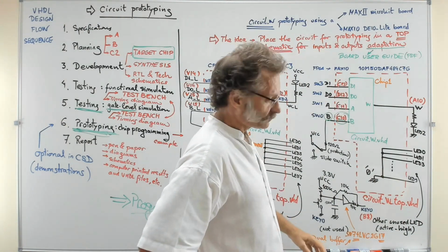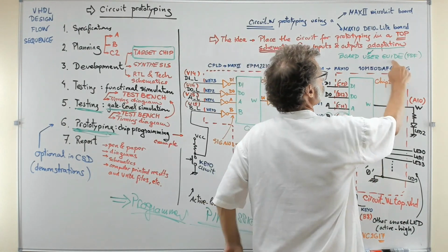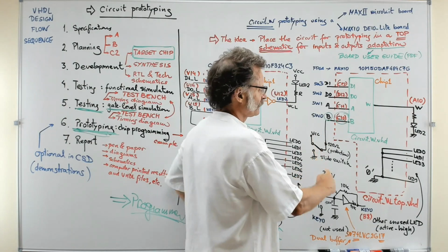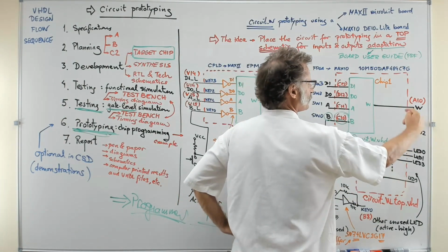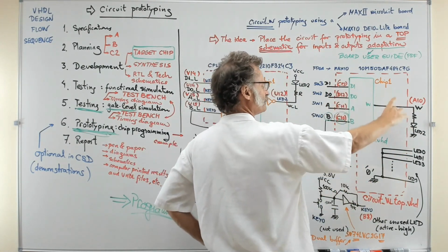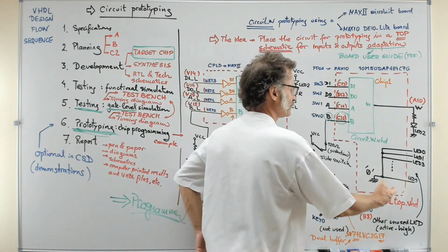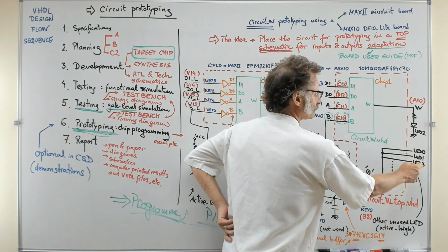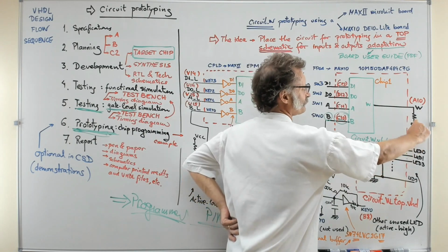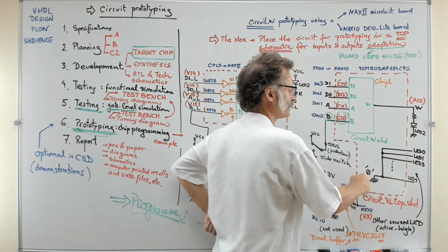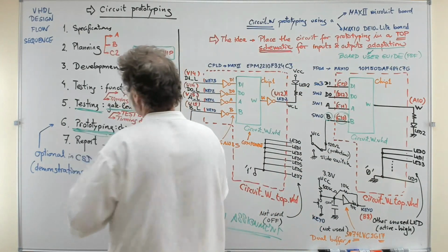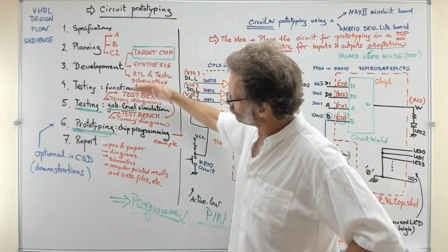chip. So the connections, perhaps after studying the user guide, are going to be different, because in this board, for example, you see the switches, and you see that the LEDs are active high. So this time for this Max 10 prototype there is no need of the inverters, for example, but you have to connect still all the LEDs that are not going to be used to the convenient level, this time a 0, because they are, as I say, active high, and with a 0 they will remain off. So that's the idea of generating a prototype after having gone through the full design process.